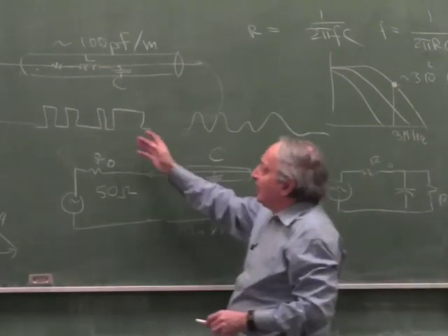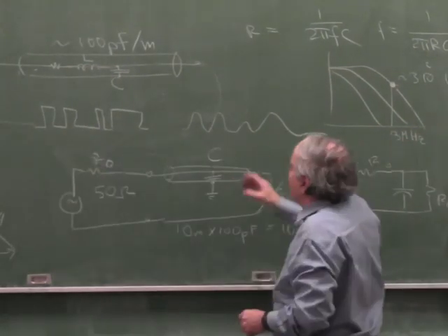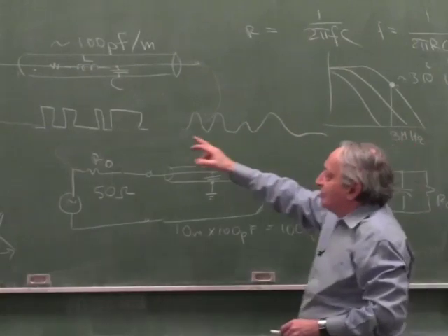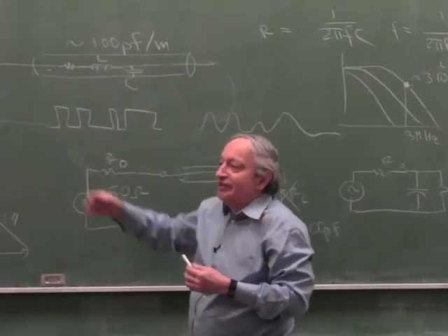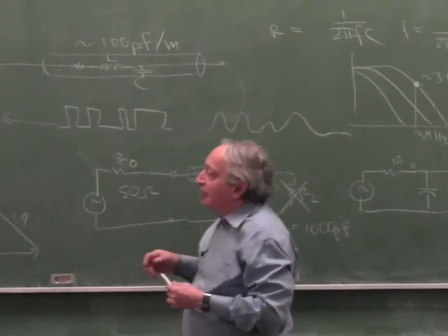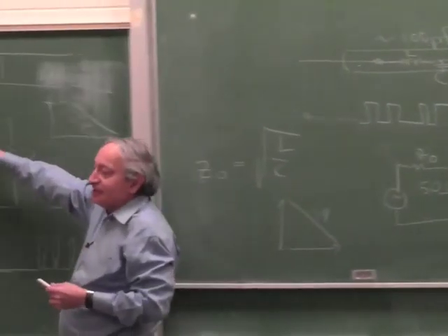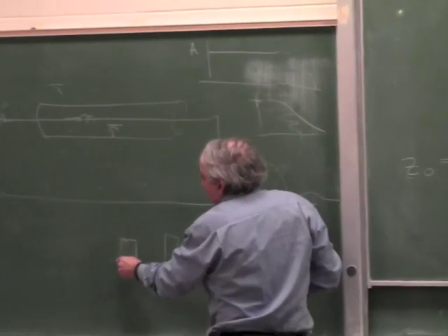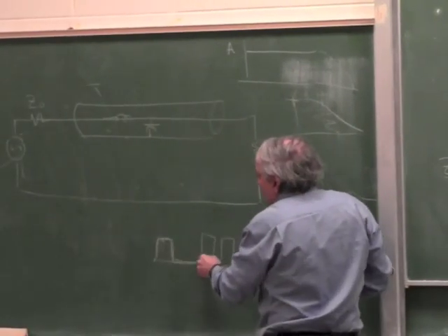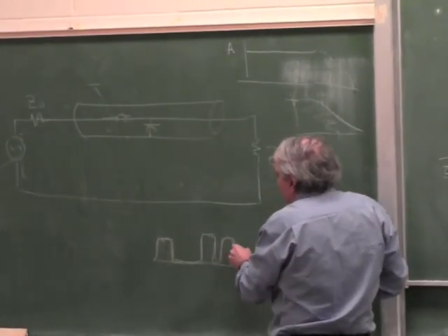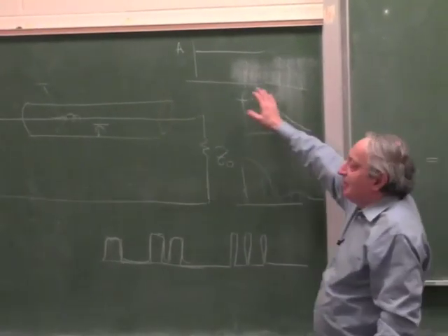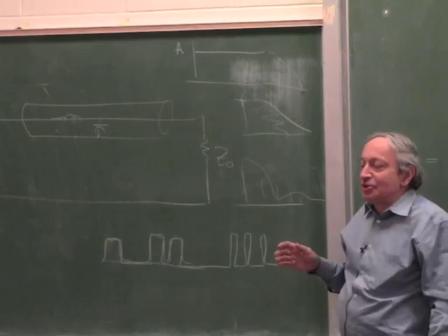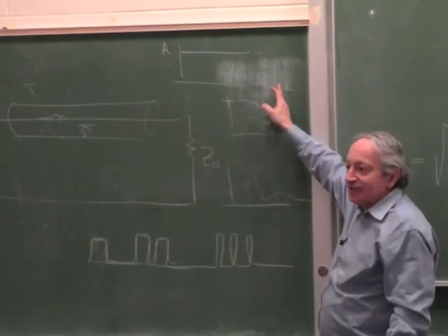And the more complex the pulse train, the more it will be affected by the distortion, because different Fourier components will propagate with different delays and different phases. Now if I send a pulse train through a transmission line, it will come out exactly the same, maybe with slight rounding because it's not infinite bandwidth. So the significance of something being frequency independent is not just that you can work at high frequencies, like in RF.